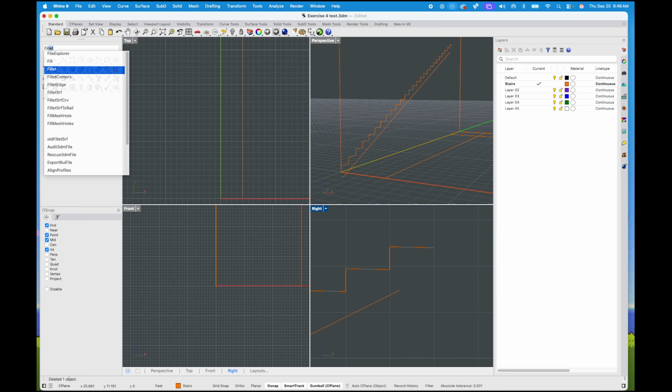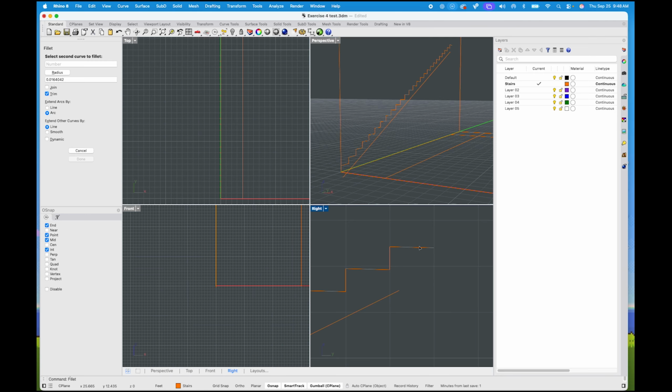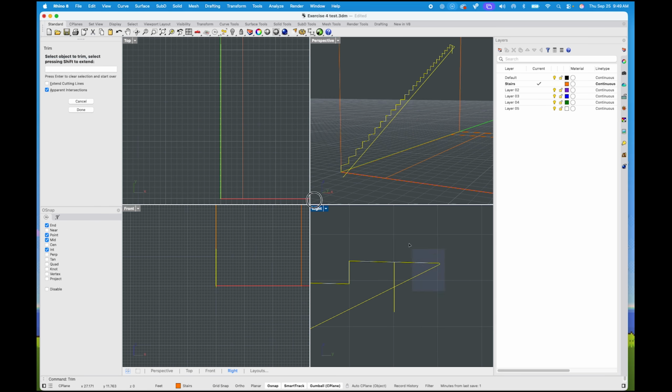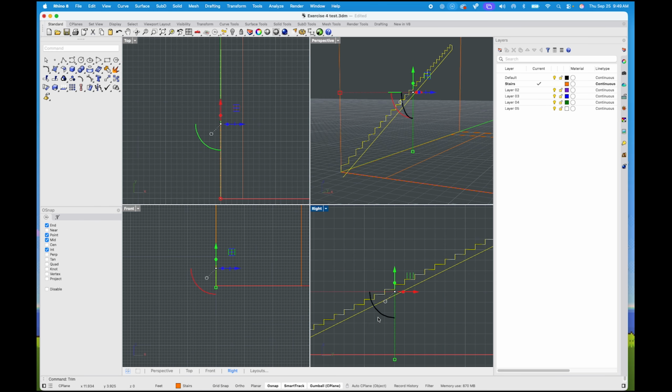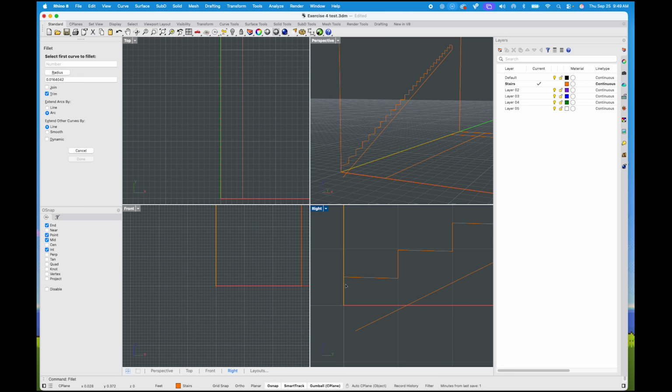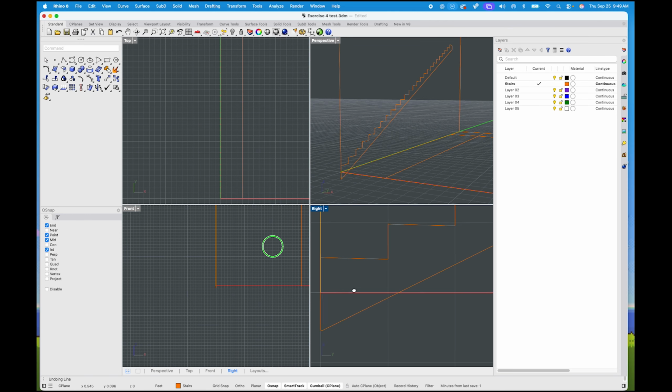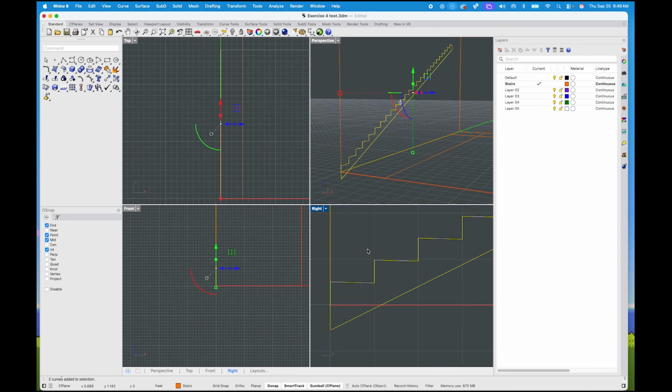We could either fillet edge, right? And it's going to match there. I could also take that original and just chop it off with some trim. So TRIM. And of course get rid of whatever I don't need. Next is this piece as well. Again, I can fillet as well, which is kind of like if you've ever used Revit, right? You can definitely use TR or trim, those kinds of things. Not sure what that connected to, so let's try that again. And maybe we can actually use that line to trim it as well. Actually, let's try it. TRIM. And let's see if we can get rid of that.